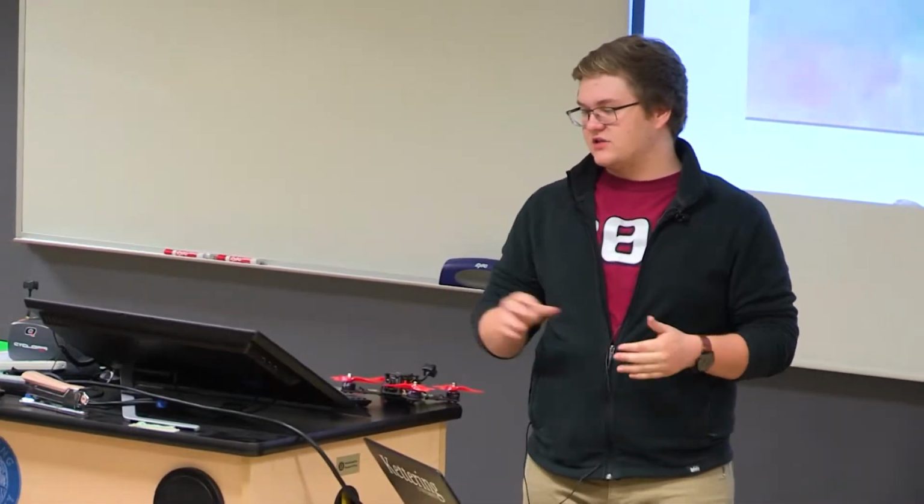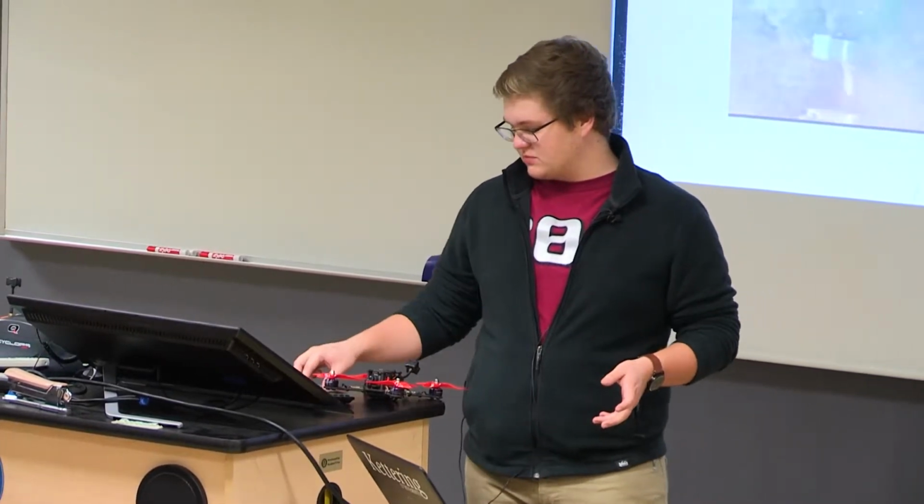Now, the cool part about these is it's not just buy a board, plug it in, and fly. You can do that, but you can also go in there and actually tune each of the control loops, by adjusting the values for the loops like you would in a lot of other systems. In this video, at a couple points, you'll see the quadcopter shudder like this. That's because my D gain, or I gain, I believe, is incorrectly tuned, and it's allowing oscillations into the system.